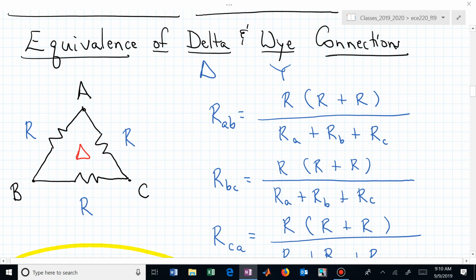Down below is the sum of those three, because in this configuration we know that it's the parallel combination of one of those with the sum of the other two. And the sum of all three is what you would put in the denominator in a parallel combination. Parallel combination of two resistors would be R1 times R2 over R1 plus R2. It's just in this case, R2 is a sum of two series resistors. What labels do I put on R sub AB?